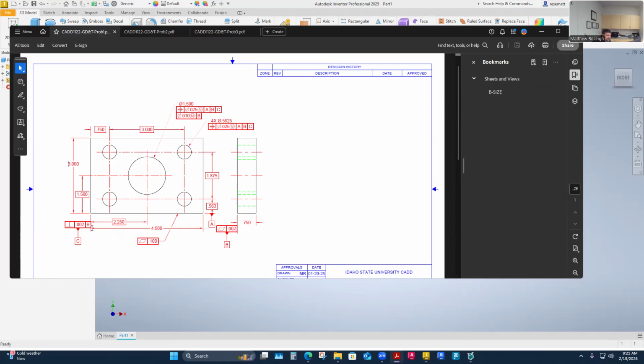These are controls here for how flat this surface would be. It's not really controlling the datum. We just happen to be using that flat surface, if it has been flattened, as datum A. You don't hook those together. These are standalone.